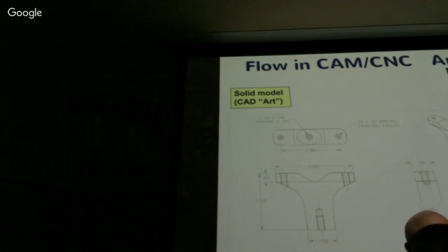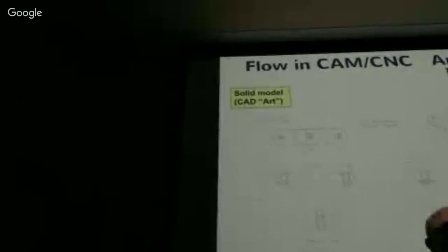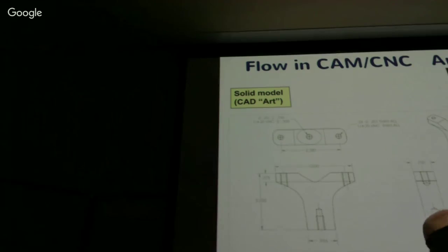We're good at CAD. We can put chamfers on everything. Chamfers are cool, right? Especially when you get in that photo rendering in the CAD software. It's all shiny and stuff. Yeah. Chamfers on the outside of parts, or sorry, not chamfers. Fillets. Fillets is the one I'm thinking of. Fillets on the outside of parts, expensive to make.